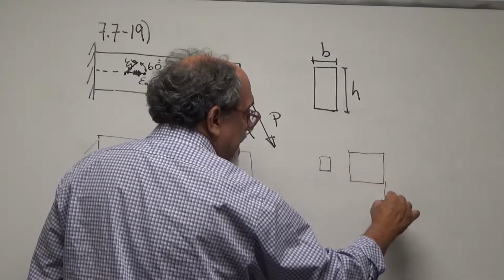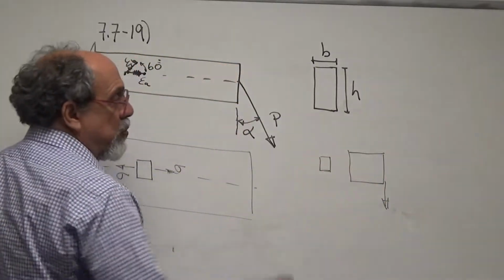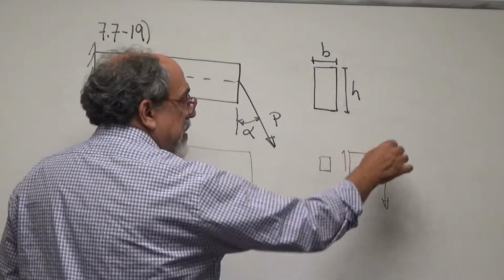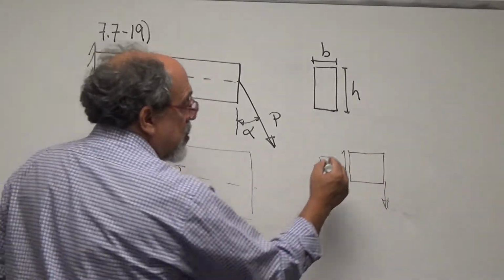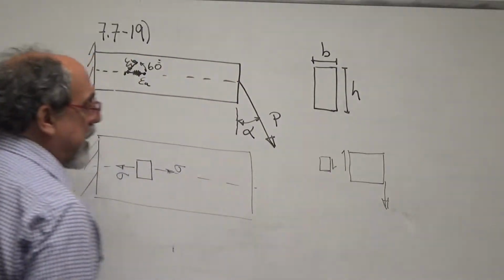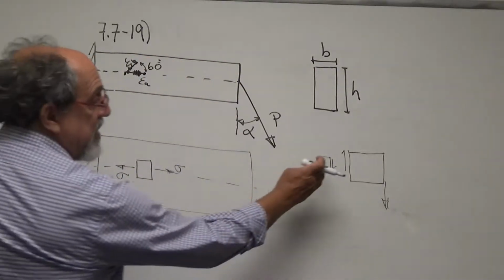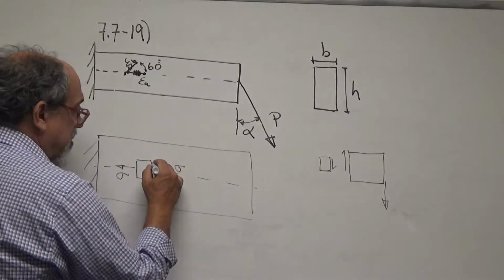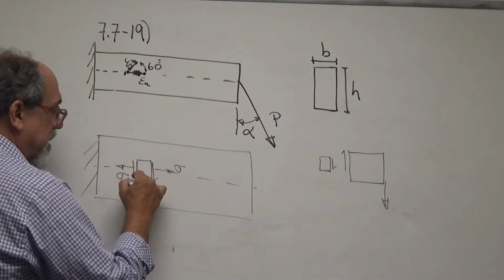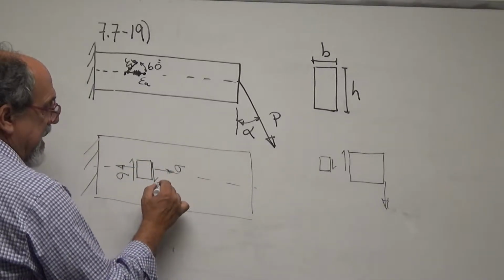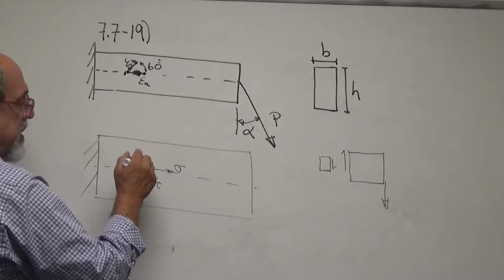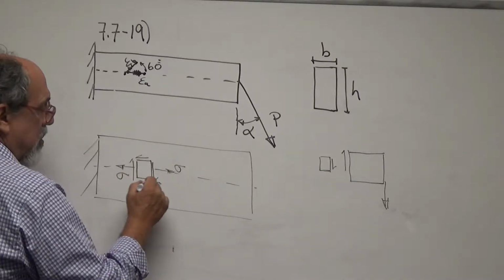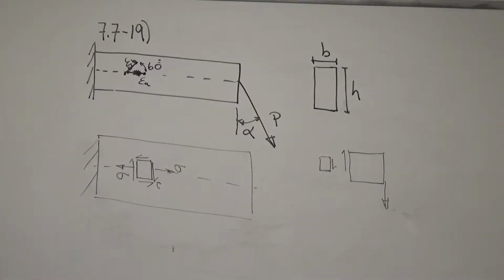So you can see that if the component of the load is downward, the shear on a free body diagram like this would be upwards. So in this element, the shear is downward like that, because this is the face that connects there. So I have a shear stress downward here, and since those are rotating clockwise, this shear would be counterclockwise, and so that is that stress element.